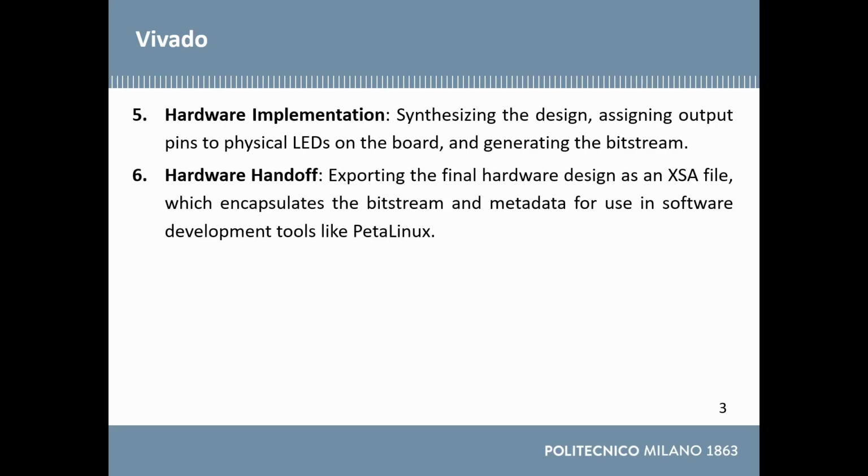And hardware handoff: exporting the final hardware design as an XSA file, which encapsulates the bitstream and metadata for use in software development tools like Linux. By following along, you will learn how to take a custom Verilog module and make it accessible as a memory mapped peripheral to the main processing system. So let's move on to Vivado.